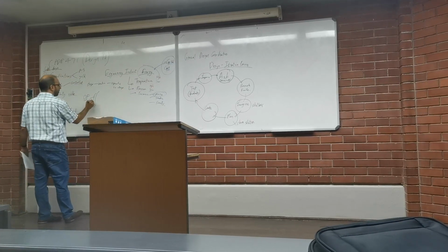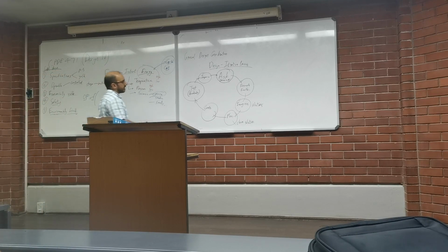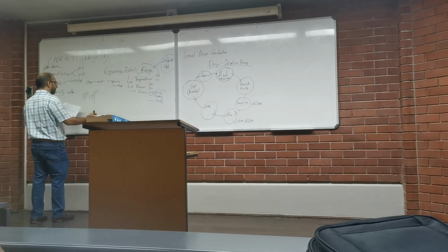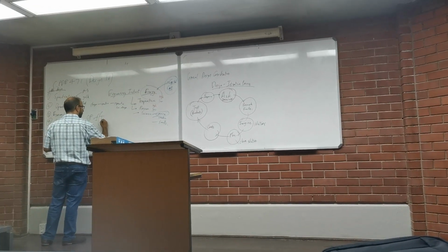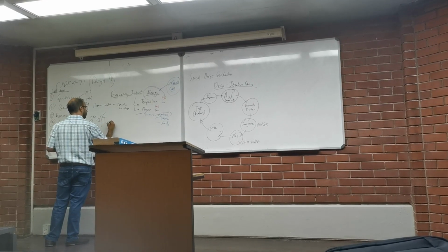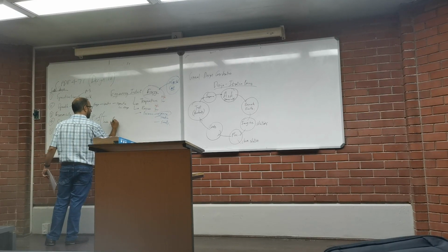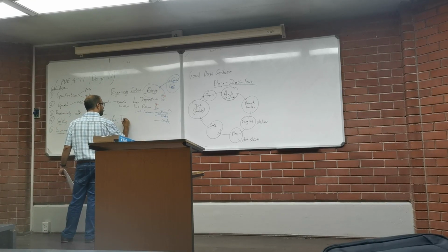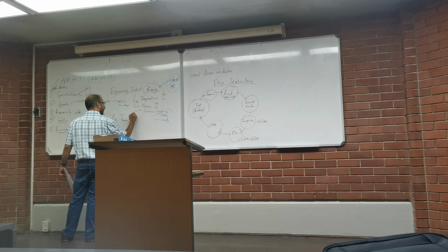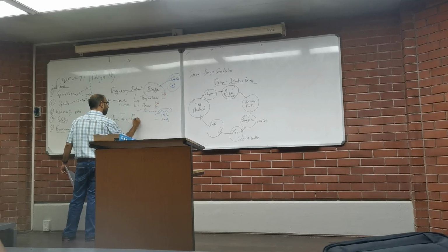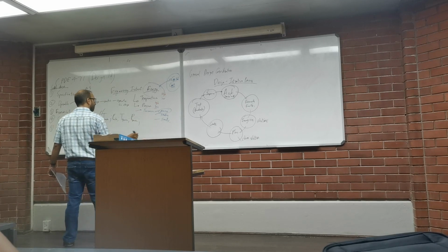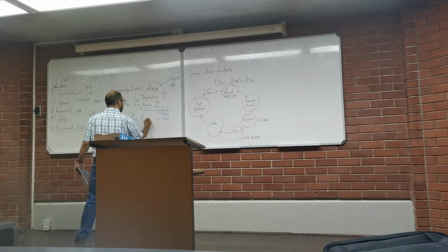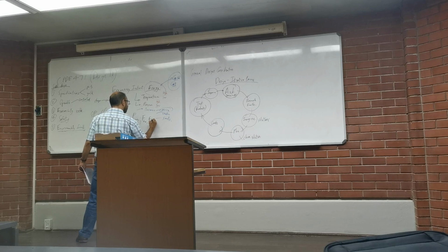Typically, in trying to continue this process, you are ultimately trying to optimize the following values: reactor temperature, reactor pressure, separation temperature, and separation pressure. And that's ultimately tied in with your feed and product flow rates and purity.